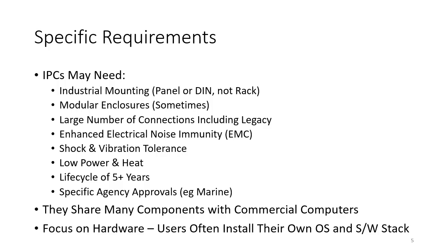Typically today, we would run Windows 10, even though Windows 10 is coming to the end of its life for desktop applications, Windows 10 is still very common in industrial applications. And what we use for those is Windows 10 IoT Enterprise, which is the same as full-blown desktop Windows 10, except we use the IoT version, which has some of the bloatware removed. So, for example, it doesn't ship with games. Windows Update is optional. And also it has the LTSC version, which means long-term service channel, which gives it extended support beyond the normal desktop versions of Windows. So there may be some aspect to do with software, but typically the focus is on hardware.